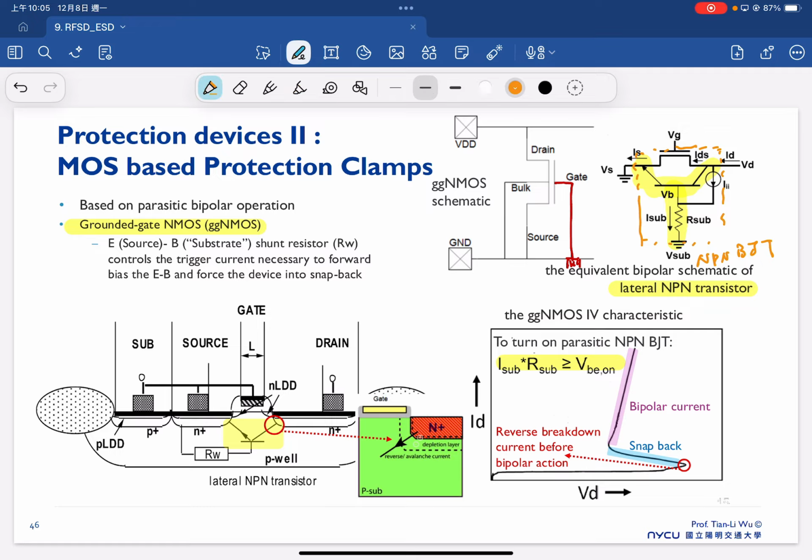So it's here. So in the end, you will find out that it's not that difficult to understand the ESD latch-up issue. Latch-up is mainly related to the parasitic BJT that would turn on by itself. But we can also leverage this characteristic: if we want to make sure that our ESD protection device can be turned on, we also use this latch-up characteristic.